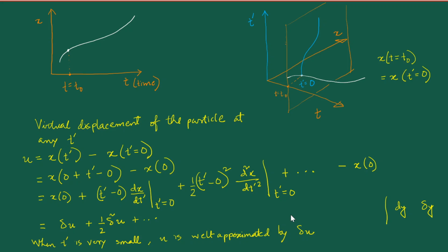At that frozen instant of time, all the forces and constraints, even if actually they are changing with time, are not changing, and then you explore the changes in the configurations of your mechanical system respecting those forces and constraints as they are at that frozen instant. And then, if you consider a little infinitesimal displacement by keeping the time constant, what you end up with is the virtual infinitesimal displacement, which is all important in the rest of our discussions.